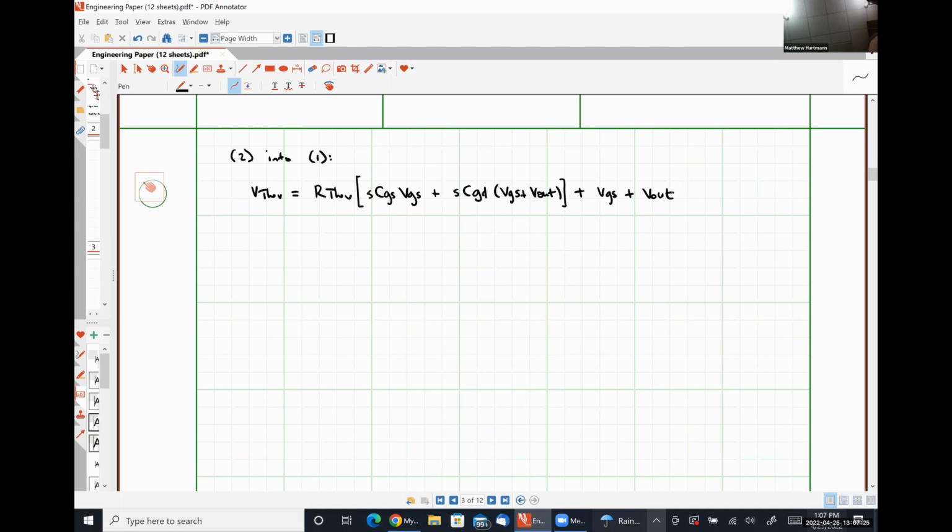What that's going to give me is 1 plus S R Thev times CGD plus CGS, all times VGS, plus 1 plus S R Thev CGD times V out.